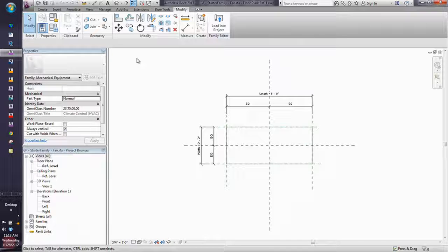That's what they downloaded, the complete AWWA library. Everything is in there right now. This just came out. We were talking to the development team and we found a flaw. The flaw is that all of the connectors are on the surface of the fitting. Why is that a problem for mechanical joint pipe? Same with hub pipe. Why is it a problem? It's the actual length of the pipe.